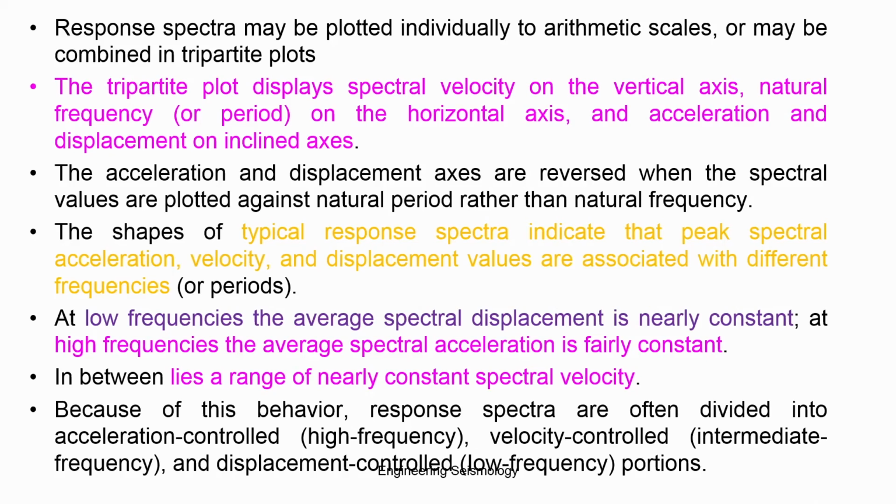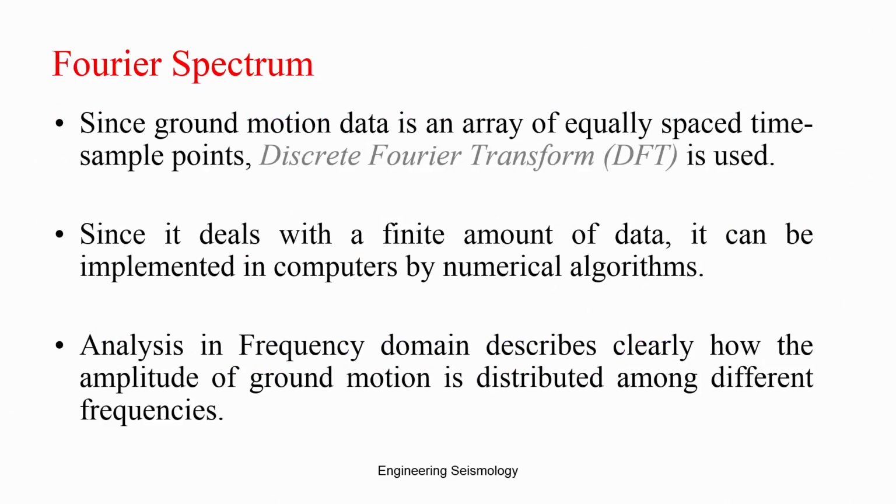Because of this behavior, response spectra are often divided into acceleration controlled, the high frequency range; velocity controlled, the intermediate frequency range; and displacement controlled, the low frequency range. So this portion comes in the tripartite plot and design spectrum development portion. You can discuss this in detail. So this is about the response spectrum.